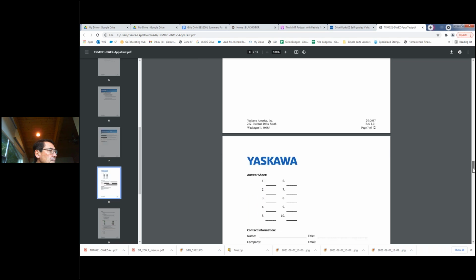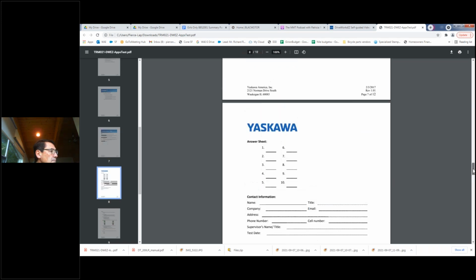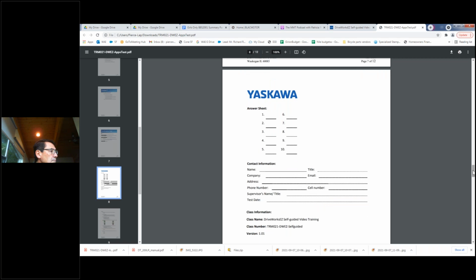It's funny, the biggest two that I wrote the most extensive code for were kind of similar in their functionality. One was for a testing unit for General Atomics, where they wanted to run a unit basically back and forth on a linear track, and it would accelerate. It was basically doing a trapezoidal move, and they had a slowdown sensor and a stop sensor at both ends, but there was no encoder feedback. So what I was basically doing was giving a run command. When the slow sensor triggered, it would ramp down and then to a crawl speed, and then it would crawl till it hit the end of limit switch, and then it would come back the other direction.